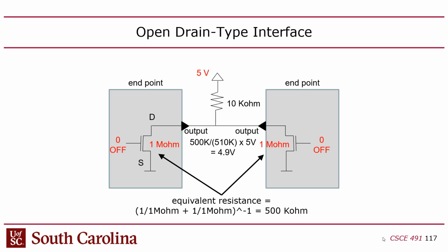So you've got a pull-up resistor there. You've got a wire that's being shared in the sense that you can have multiple drivers of that wire, and you've got a pull-up resistor to VDD. If nobody is talking, no one's driving, then the voltage level of that wire will be reasonably close to VDD, right? It won't be right at VDD because there's a resistor there where you'll get a voltage drop, but